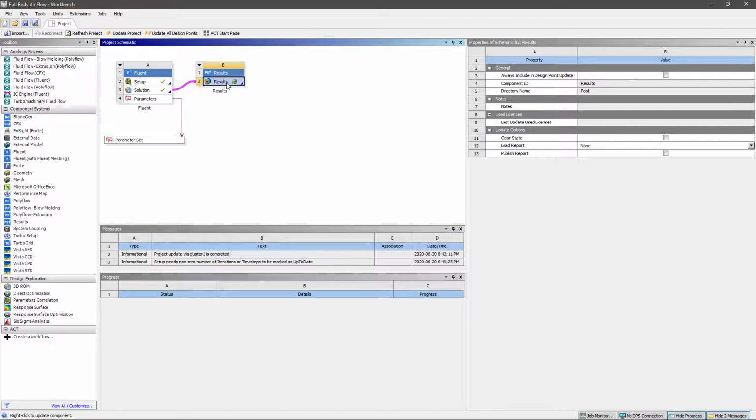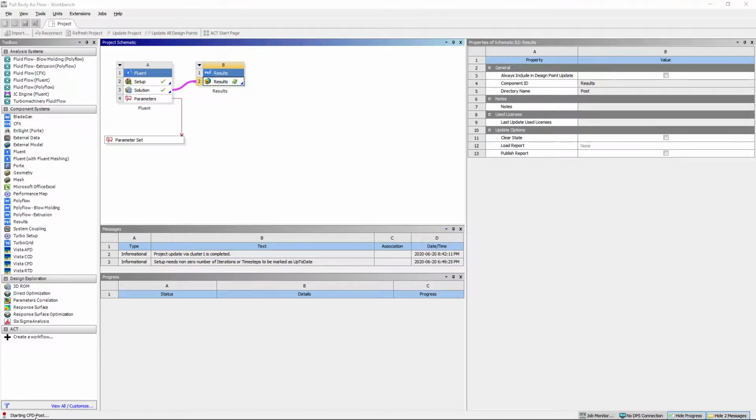It may take a little bit of time due to the fact that it has to load the mesh. As you develop CFD-Post processing entities, and as your post-processing file becomes more complicated, it will take longer and longer to open CFD-Post. So just be aware of that, and no need to worry if it does take a while to open. So double click this and you'll notice it'll start to open in the bottom right.